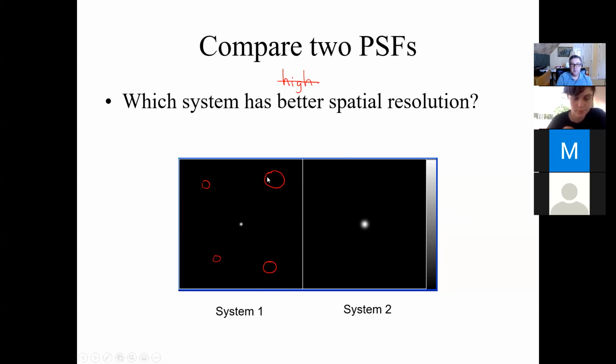Okay, and so it spreads more here and here, and somewhat less here and here, and maybe the least in the middle. Whereas if it was shift invariant, these would all be the same. So if I put a point in at this location, it spread this much. If I put a point in at this location, it spread this much. So a linear shift variant system would have different point spread functions, or the point spread function is a function of location.